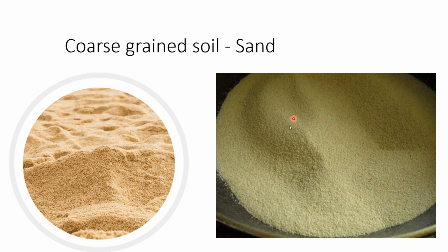So we can consider sand a good material. If we have sand at our site, then it is very good to work with. And again, we have to see whether that sand is in a dense condition or a loose condition. Denser means it is tightly packed. Tightly packed means it will have very low permeability, and it will have very good strength.